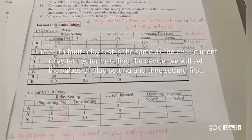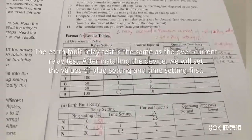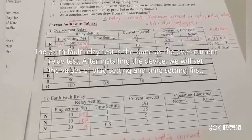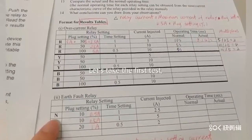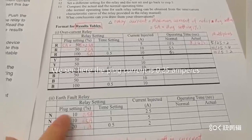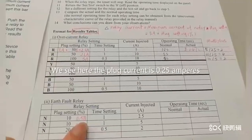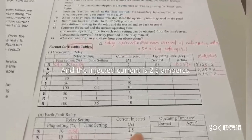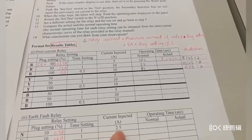After connecting the devices, we set the values of the plug setting and time setting first. Let's take the first test for example. We say the plug current is 0.5 amperes and the time setting is 1, and the injected current is 2.5 amperes.